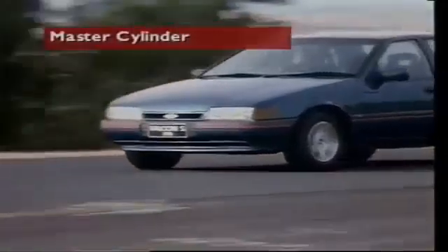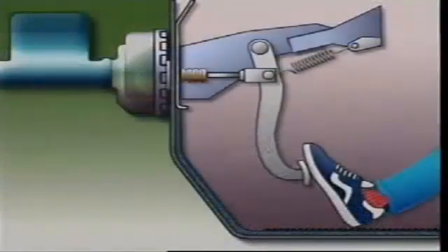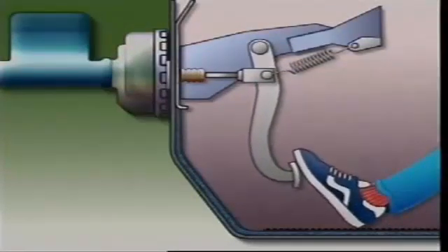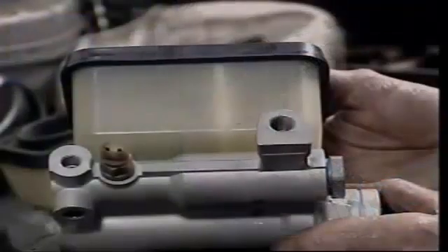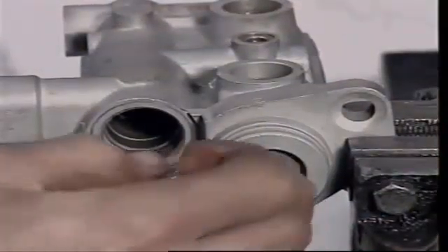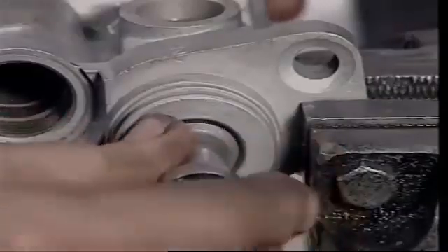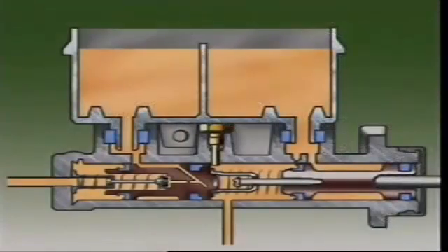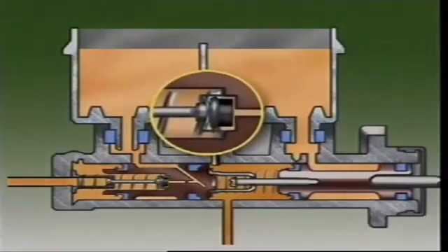This section looks at the master cylinder in ABS. The master cylinder is connected to the brake pedal via a push rod. The ABS master cylinder is similar to the tandem master cylinder used in divided systems. It has a primary piston and a secondary piston. The secondary piston incorporates a center valve. This controls the opening and closing of a supply port drilling in the piston.